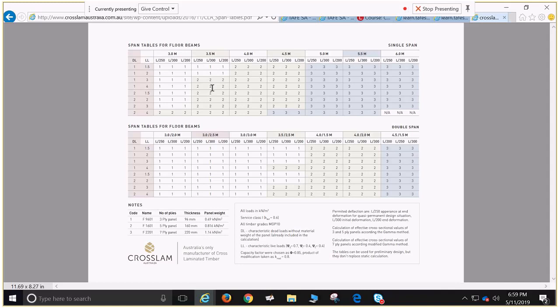It's not so much about this is we design close to failure. With commercial properties, it's about how much deflection will we accept, and everything deflects. Even this concrete slab that we're on right now will deflect ever so slightly under dead loads and live loads. So that's the way things are expressed in here. But it does give you an idea of what your capabilities are.